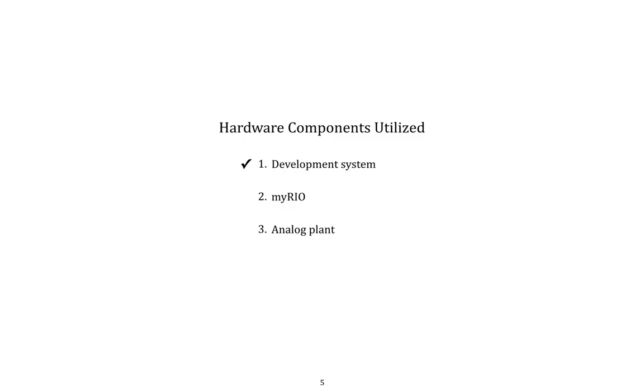If you worked with LabVIEW in the past, you're familiar with its concept of a virtual instrument. Every program in LabVIEW is a virtual instrument, and every virtual instrument in LabVIEW is comprised of a block diagram and a front panel. LabVIEW is a graphical programming language. You program on both the front panel and the block diagram. When you have your program debugged and ready to execute, you go to the front panel, and on the toolbar you click on a Run button.